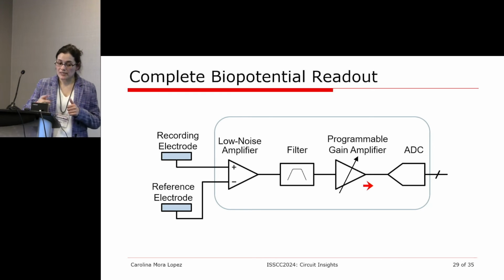And in the digital domain, it also becomes expensive, because the more bits you have, the more computation and the more power you need to process these output bits. Especially if you have many parallel channels, that can also become a bottleneck, a very high data rate that you don't want to deal with. So optimization of the ADC resolution is very important.